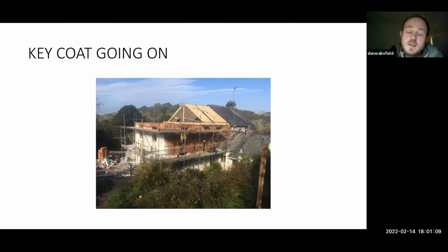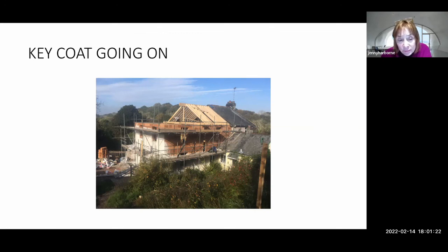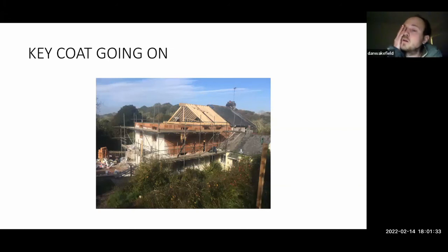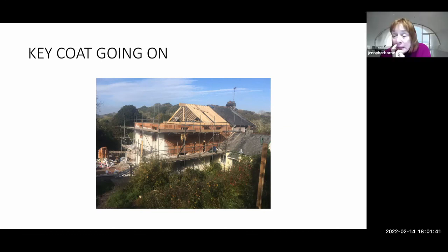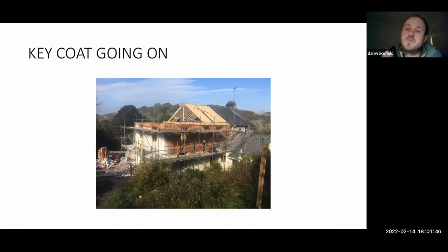I think probably looking at trying to optimize the thickness of that lintel would be the first step, so you don't use a lot of concrete. Again, it obviously is a shame to have to use a bit of concrete, but it's not a lot, because the clay block is a lot of the volume. I think we used maybe 1.5 cubes in all the lintels or something, given the overall wall area.